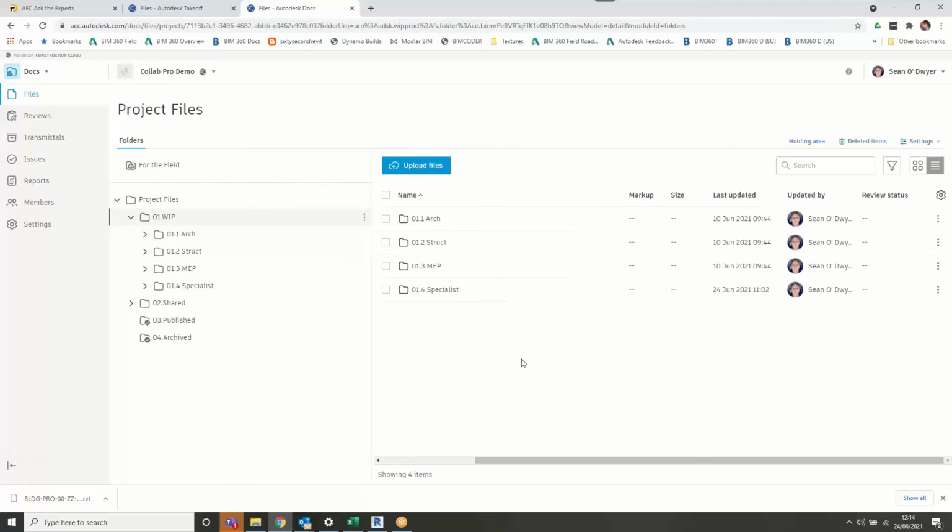And I wouldn't recommend that either, because if you have IFC models linked in as references, if you're using a Collaborate Pro workflow, and you have a non-Collaborate file, like say an IFC structural model linked in, when you go to view those files within BIM360, within say the files area of Autodesk Docs, it won't have that IFC desktop connector linked model as a background on your sheets, because it's not linked through your external references in Revit.